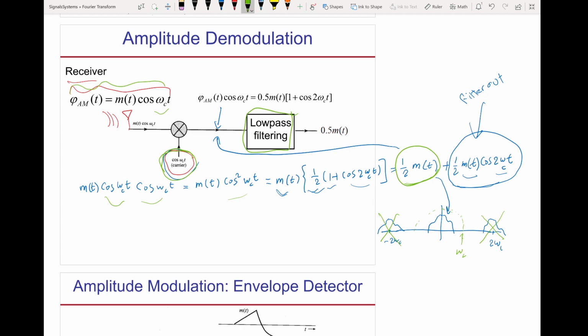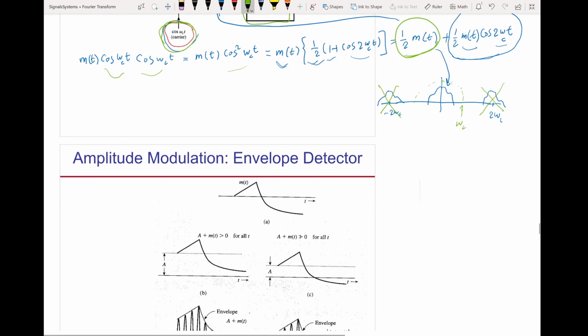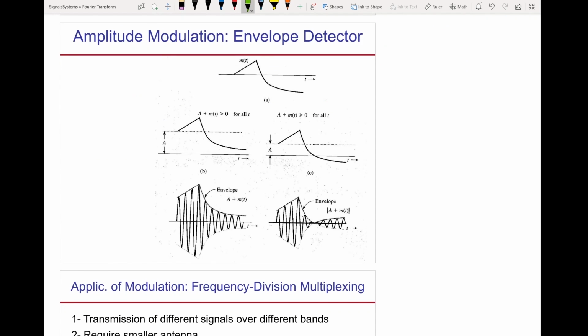Well, we use amplitude modulation again, but first we shift up the message signal, and that's something like this. So I take the message signal. Usually the message signal will have positive component and negative component. So I shift it up so there is no negative component. So I add to the message signal a plus m of t, such that a plus m of t is larger than 0. There is no negative, so that will be the signal. Now I do amplitude modulation. I multiply it by cosine. So when you do this, then that will be the signal, the modulated signal.